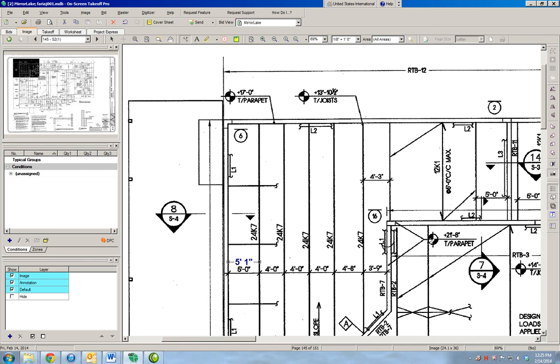Okay, so from this roof framing plan, what we want to do is identify the components that are going to be required to be estimated. We see here these elements 24K7, and as per the previous video, we know that these are steel beams that have the identifier 24K7.